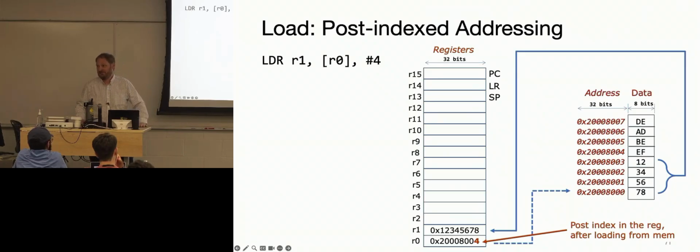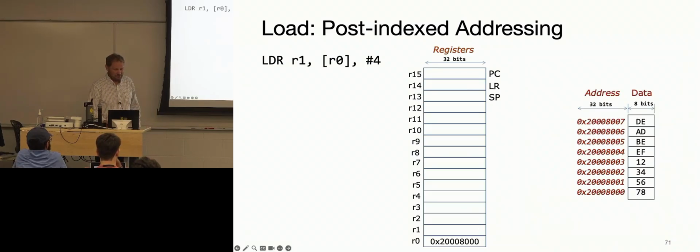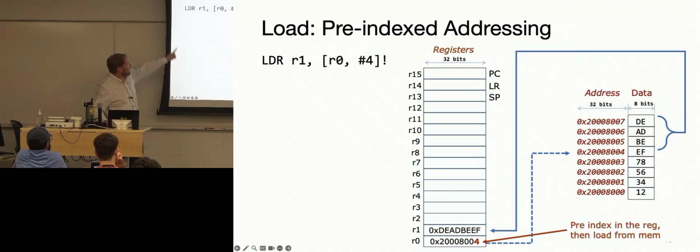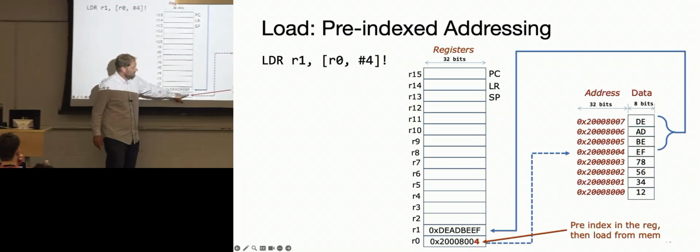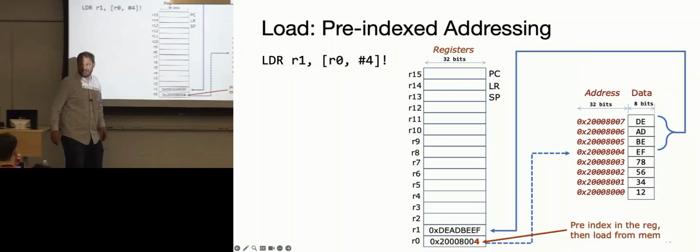Thank you. So the post-indexing and pre-indexing, you're going to do 2 different things because the order of the way the memory is being updated is different, right? Well, because for post-indexing, you grab 0 through 3, right? And then after you update it, yes. If you have 4, you grab 4 through 7. Yes.